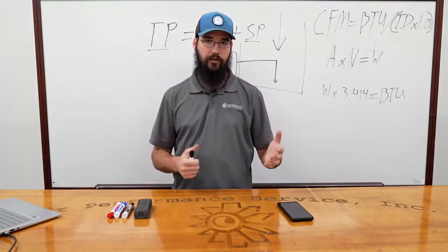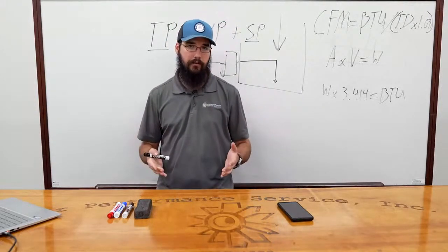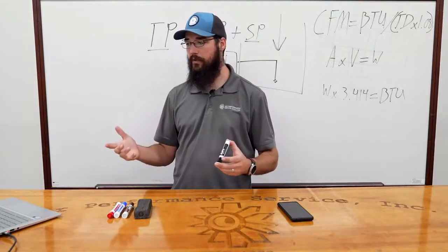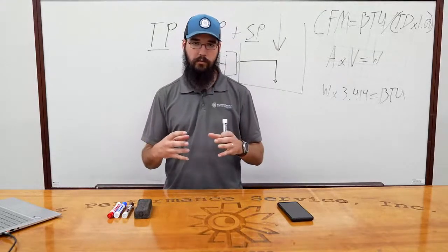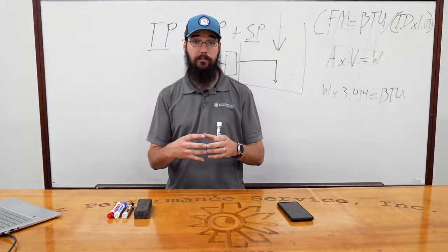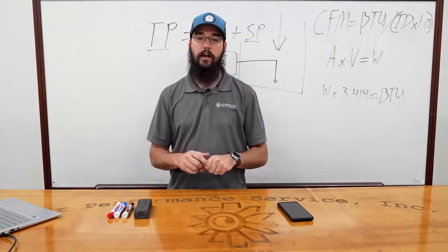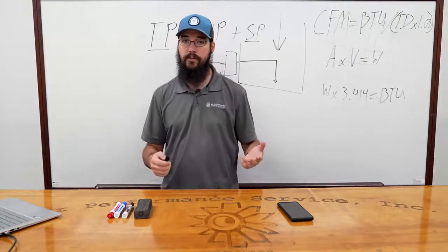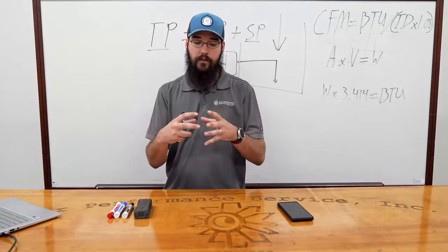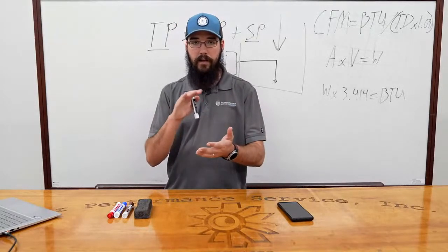And you can use external static. You can use the heat rise method. If you walk up to a system and you see that the adjustable pulley is sitting at its bare minimum, like the thing's wide open, it's very likely that it wasn't adjusted. And vice versa, they're not meant to be all the way in by default either.